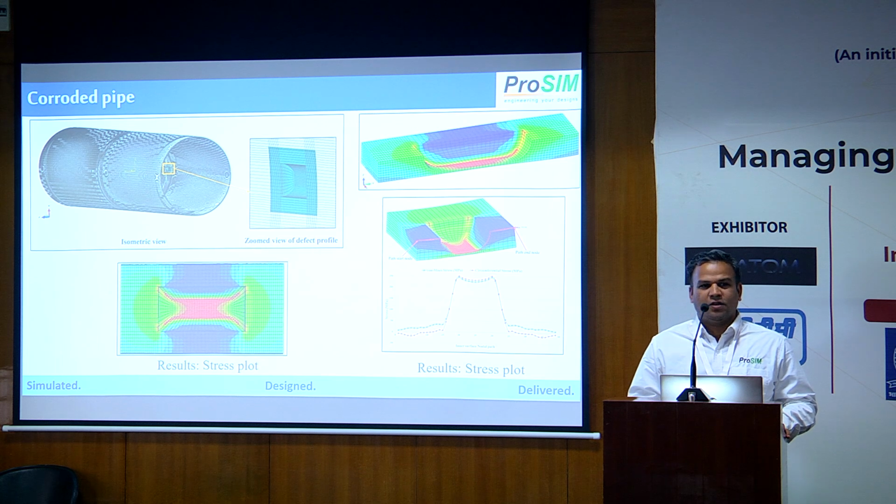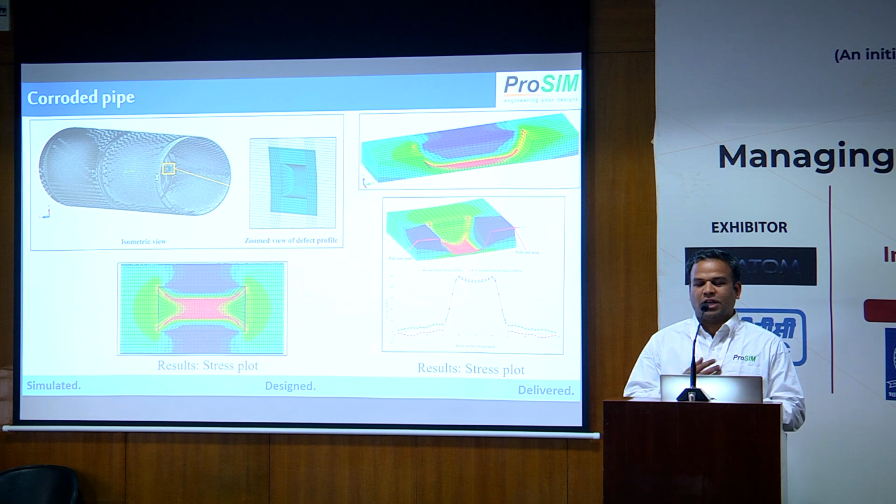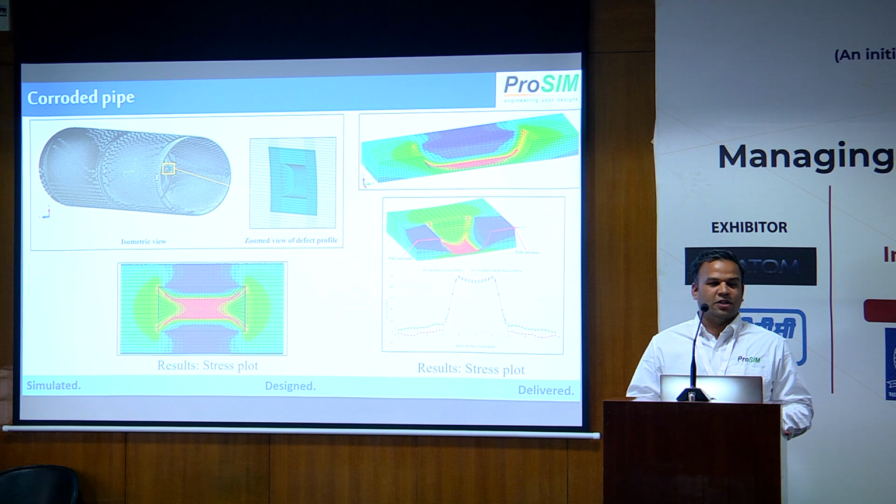Similarly, SCC in nuclear plants, I am not showing an example here, is affected by high temperature components, because some plants work at higher temperatures with pressure and cyclic temperature load with transients, which causes SCC in some components, leading to crack failure. And in nuclear plants, the impact of radiation on the metal accelerates SCC, which again causes failure of the material.